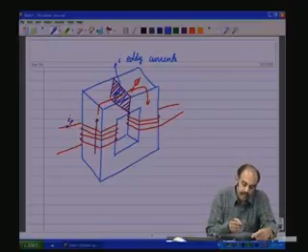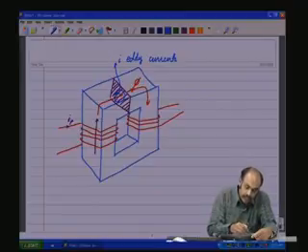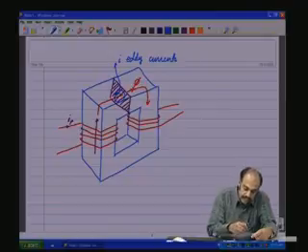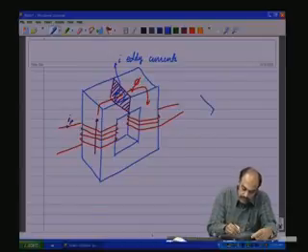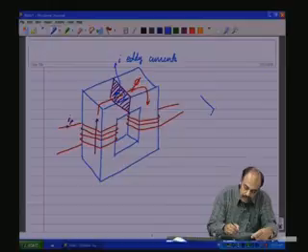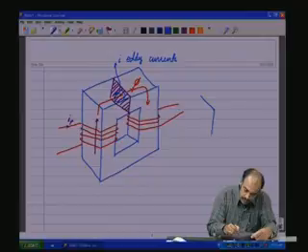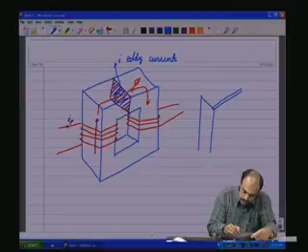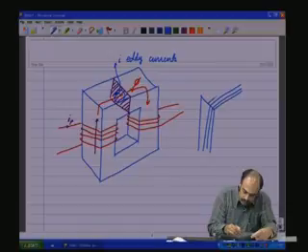So, to reduce the eddy current losses, what is generally done is to increase the resistance of the path where the current can circulate. So, to increase the resistance of the path, what is done is to have laminations, like that, and so on.